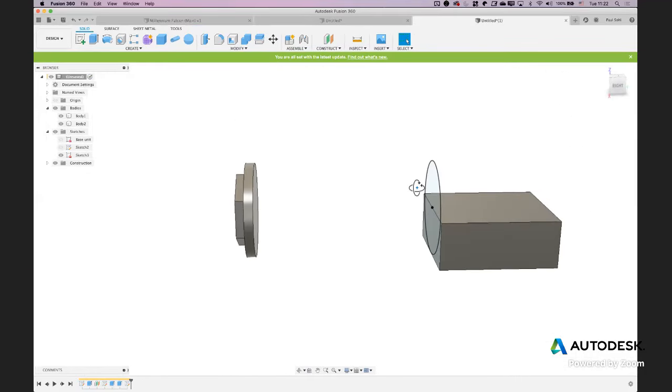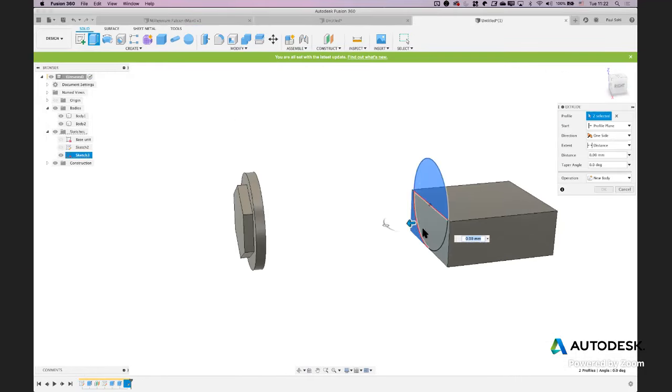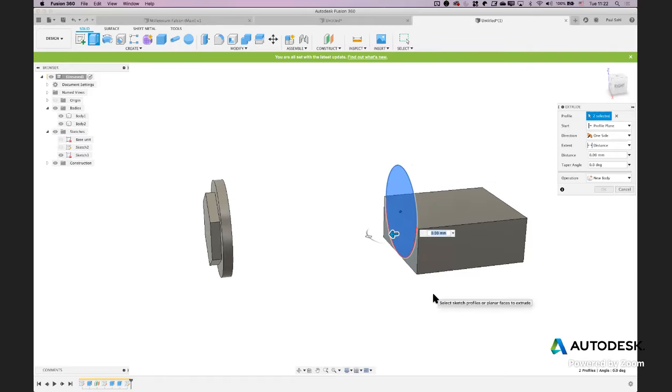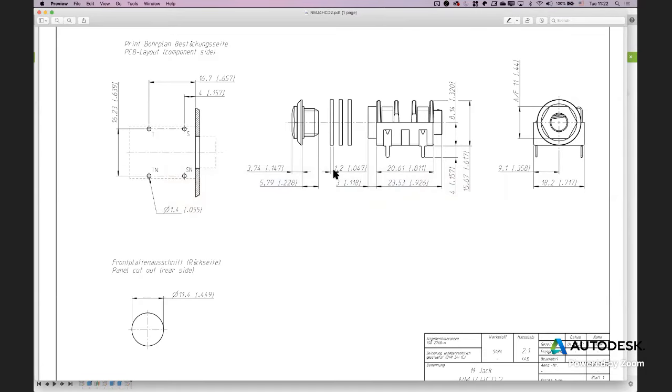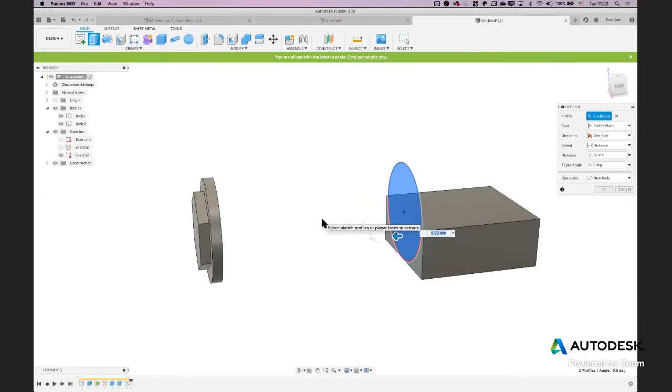Now at this stage, I'm going to go ahead and extrude that one as well. So just pick the 2 surfaces there. I can deselect that one that I clicked on incorrectly. The unit there, for anyone wondering, is 1.2 millimeters. So again, just type 1.2. And you'll notice, again, because my piece is touching up against that face, it says operation, do you want to join? In this case, I don't because they're separate parts. So I'm just going to change that to new body.